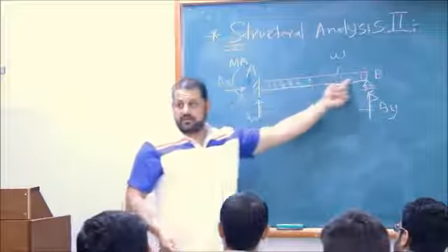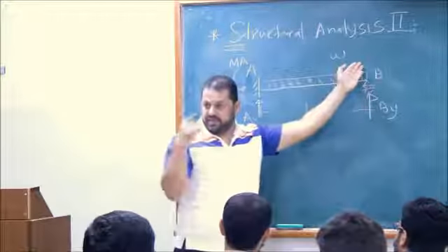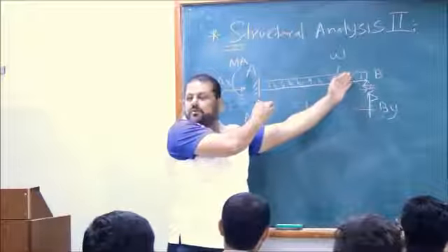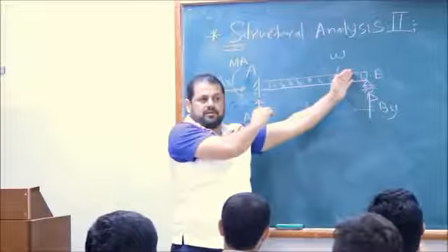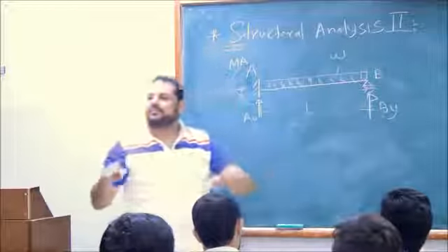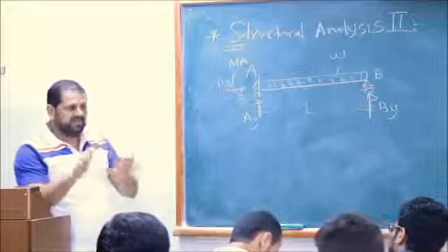It's a structural member. The load is perpendicular to its major axis. So if I tell you there is a load like this, it's no longer a beam. Do you know what it's called? A beam column. It's a frame member. The axial load in beams is very small and ignored. That's the definition of a beam.